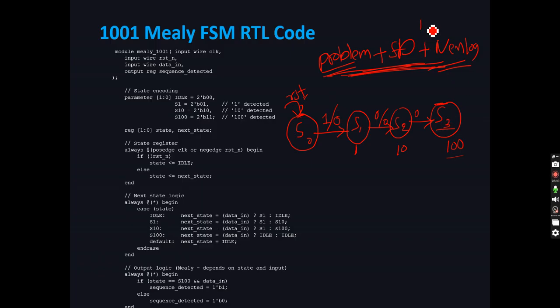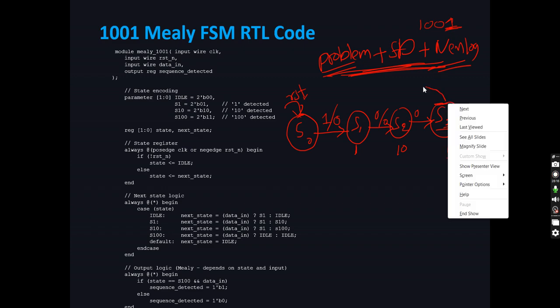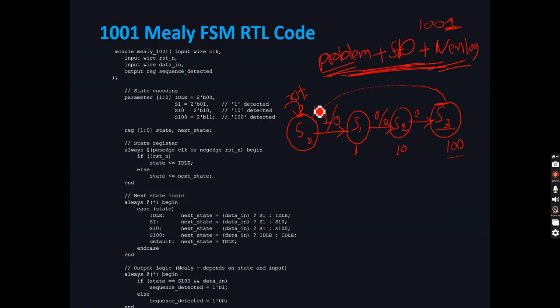After going there, it has detected up to 3 bits. Now it should detect 1 again, right? So whenever it detects 1, it will go to the reset state, and the output will be high. Here, compared to Moore, the number of states is less. That's the complexity difference. Let me complete this diagram, then I will explain what is actually happening between Mealy and Moore.